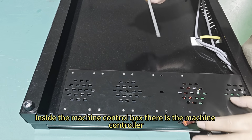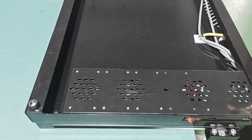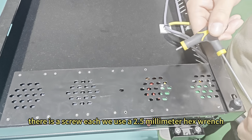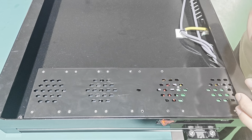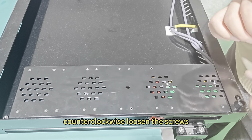Inside the machine's control box, there is the machine's controller and some drivers. At both ends of the machine, here and here, there is a screw each. We use a 2.5mm hex wrench. You can remove these two screws counterclockwise. Loosen the screws.